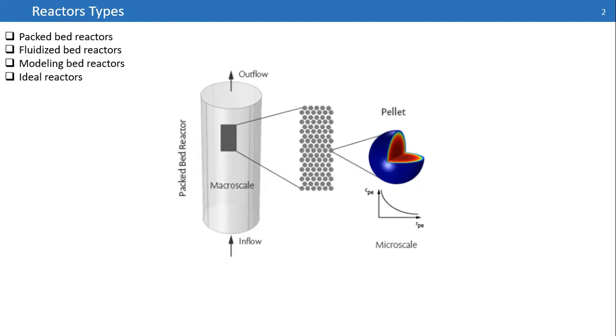So which type of reactor to use depends on your kinetics. When you are using a CSTR, you have good mixing, but in a PFR you don't have axial dispersion, and as the reaction happens, you can keep the concentration of reactants as high as possible.